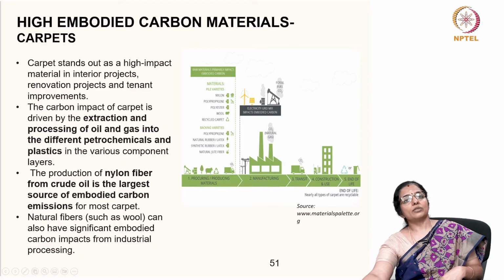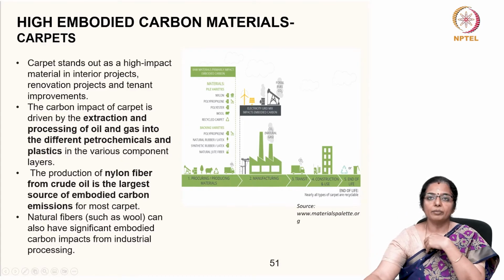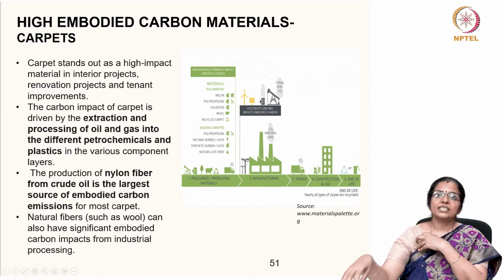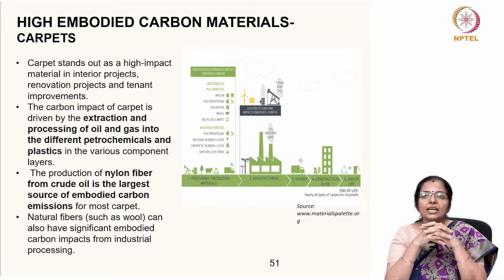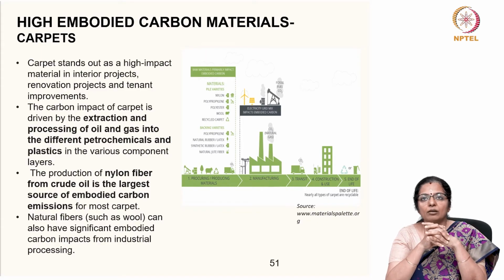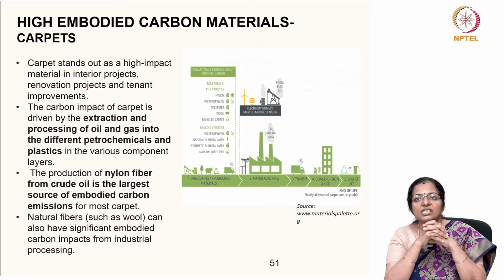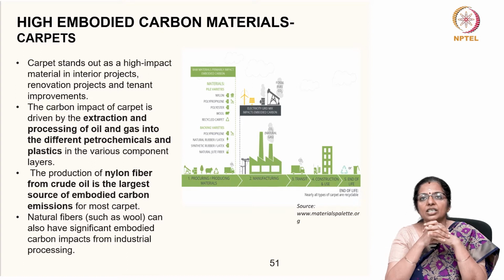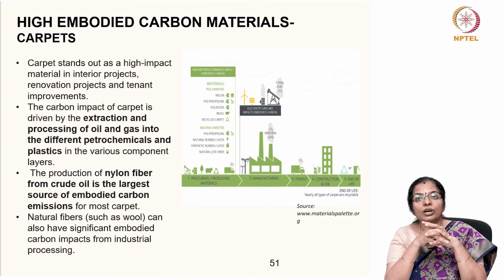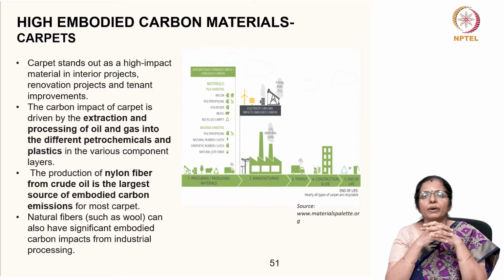Carpets can sometimes be very high embodied carbon materials. It stands out as a high impact material in interior projects, renovation projects. The carbon impact of carpet is driven by the extraction and processing of oil and gas into the different petrochemicals and plastics in various component layers.